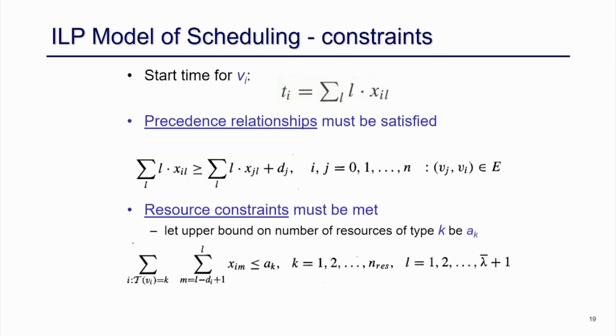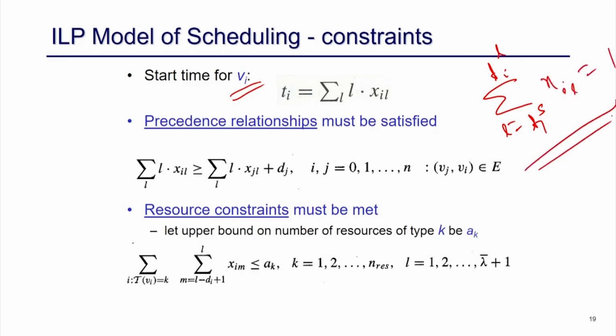Now, that is also very important. As I mentioned, for variable l equal to TIS to TIL, from ASAP to ALAP, the summation of x il equals 1, right. This is what I assume. That means this operation must be scheduled in at least one time step; only one of the variables from this range will be 1.